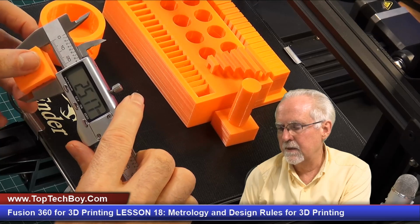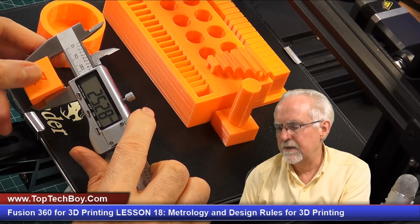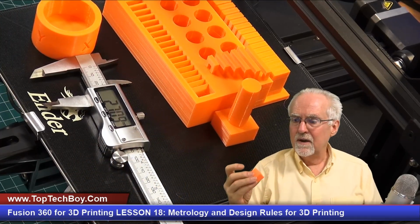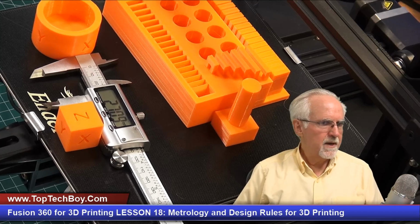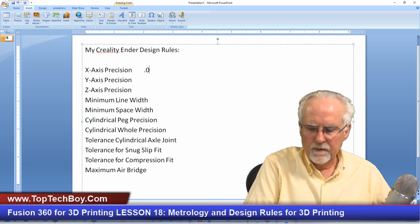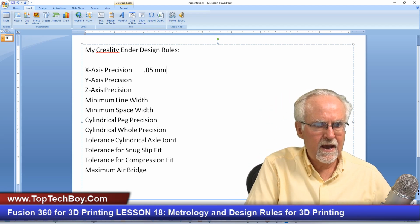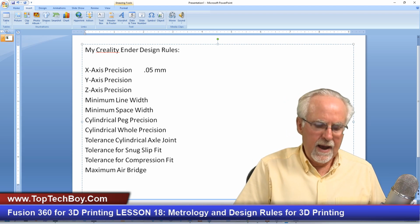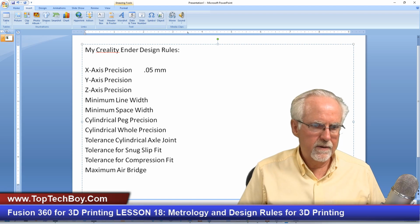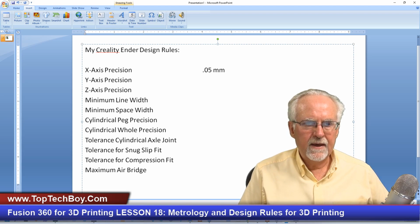I'm going to come in here. I'm just trying to look around. 25.04. I'm just looking at different areas. 25.04. And so just looking along the x-axis, I'm going to say my x-axis precision is going to be, I'm going to call it 0.05. It's kind of amazing that it's really that accurate, 0.05 millimeters. So I am designing to a precision of better than 1/10 of a millimeter. I'm manufacturing to a precision of better than 1/10 of a millimeter.